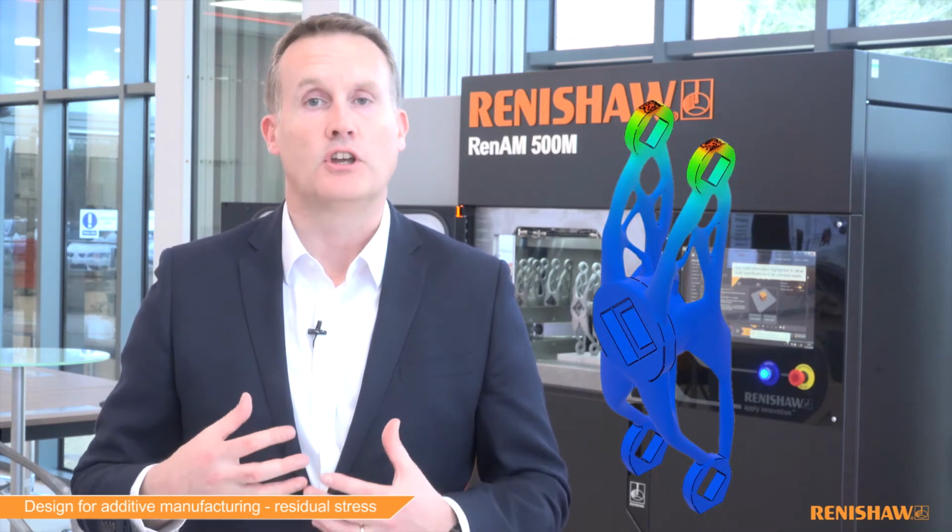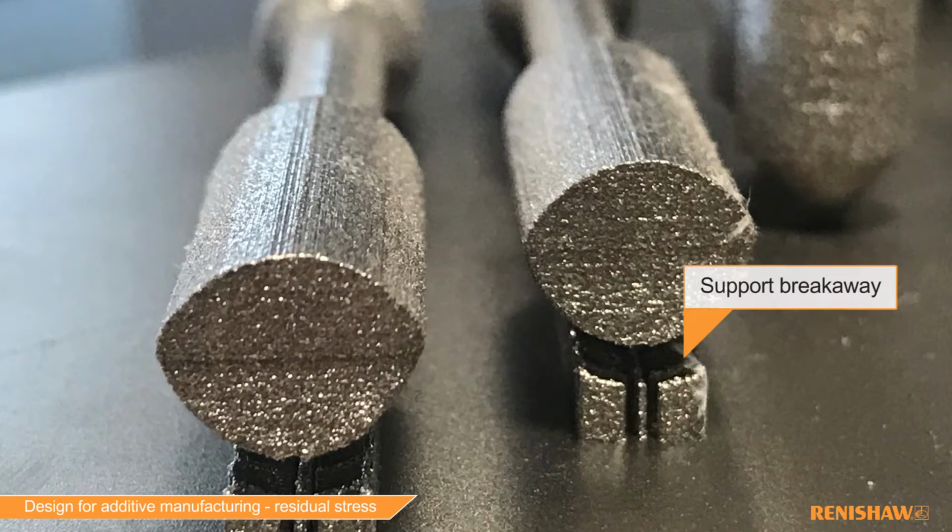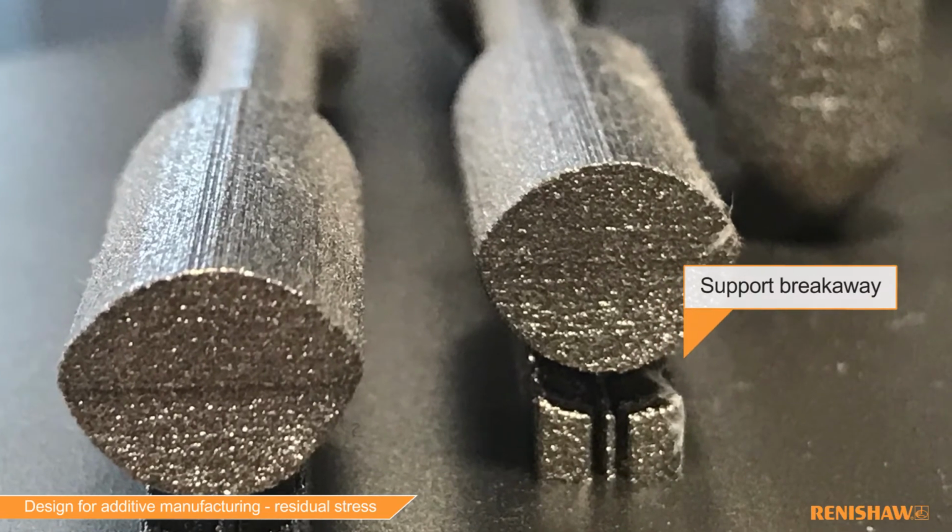Residual stresses can be destructive. As we add layers on top of one another, the stresses build up and can lead to distortion of the part, causing it to curl up at the edges and pull away from its supports. In more extreme cases, the stress can exceed the strength of the part, leading to catastrophic cracking of the component or distortion of the build plate.